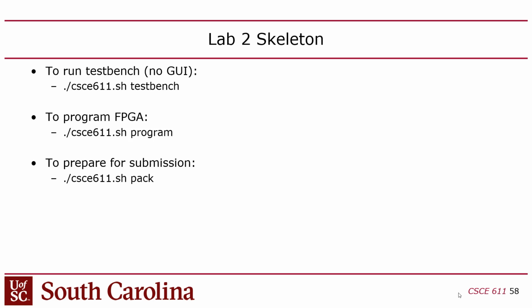It just runs the test bench, and the expectation is that your tester is going to test everything automatically, and if there's an error, it'll print an error message or something, right? The problem with that is that if you get an error, then how do you debug it? There's no way to do debugging in that case, right? So in other words, the test bench command will run the test bench, but if you end up with an error, you're going to have to open ModelSim and go through the steps that I just showed you, right? To actually see a waveform, if you want to see a waveform. You guys with me?